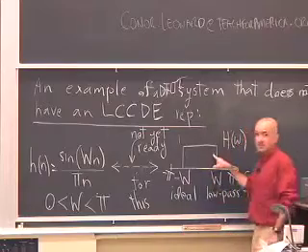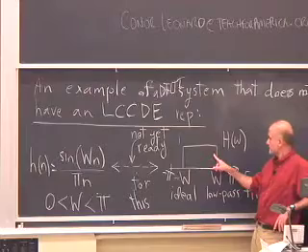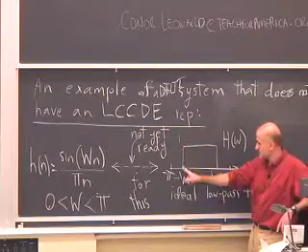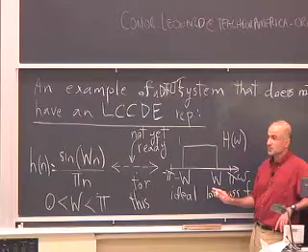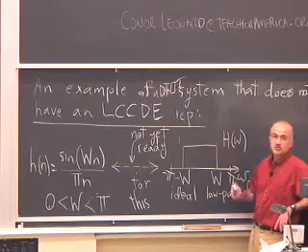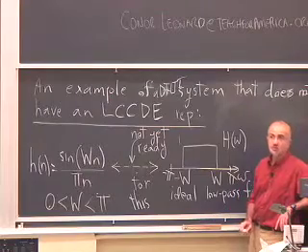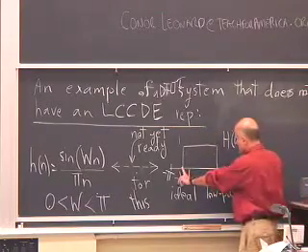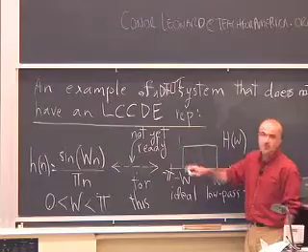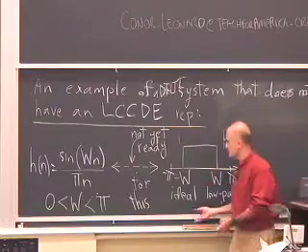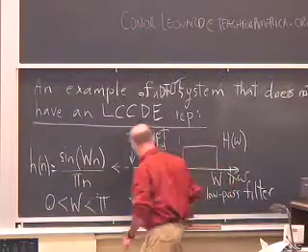But you're fully equipped to understand this. The frequency domain representation of this filter is flat, so all frequencies between minus W and W pass without alteration, no phase change. It's a real value, no phase change. They go straight. And everything outside that band is killed. So if you have high frequency content beyond W, it gets killed. It doesn't appear in the output. And anything inside just goes unchanged. So let's keep this here.